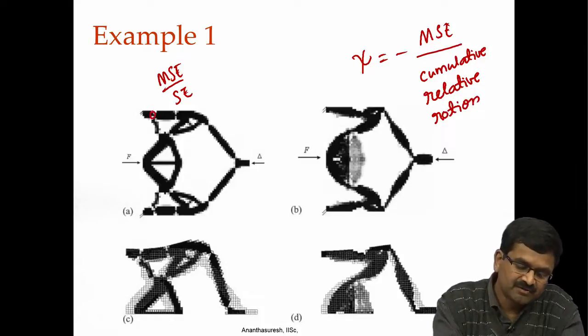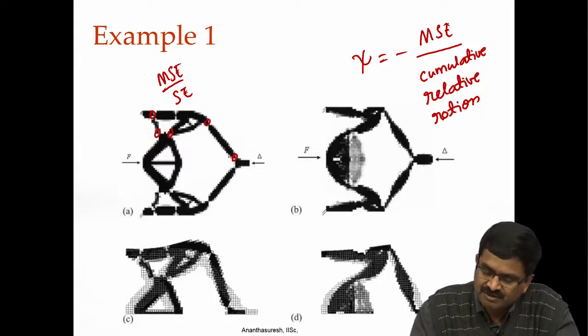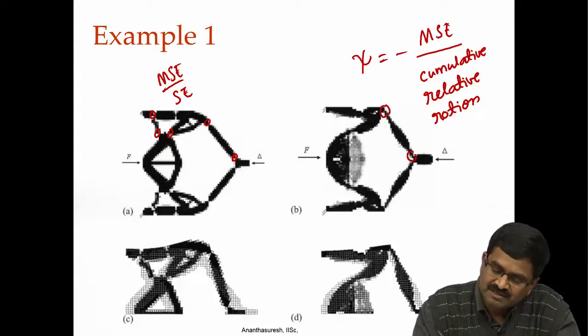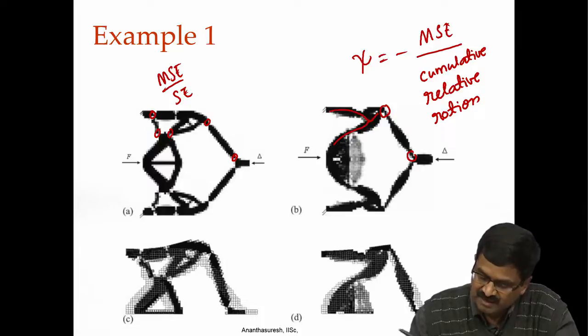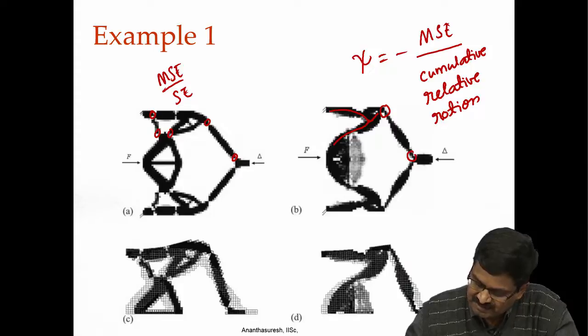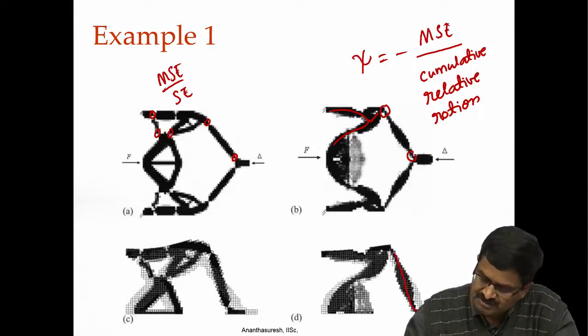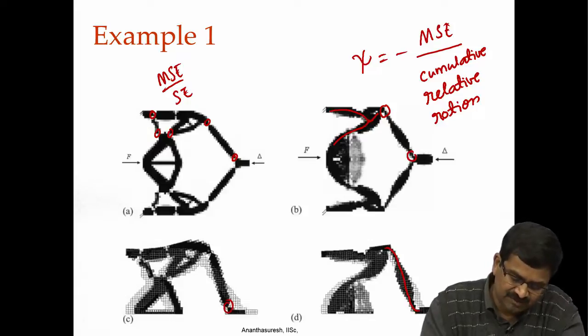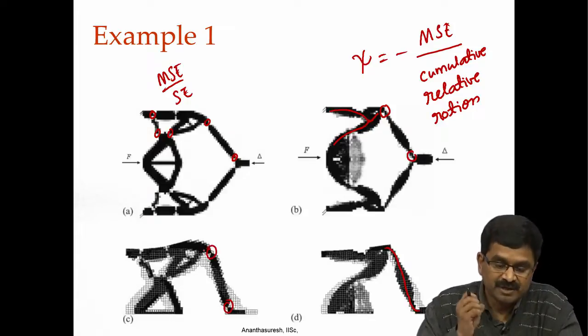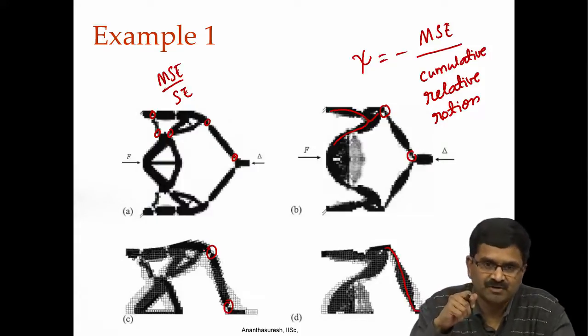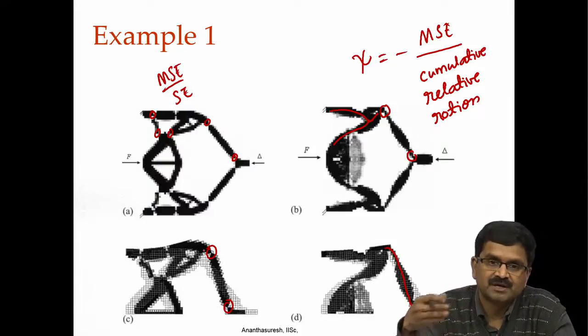You can see that we have joints, lots and lots of joints, right. Whereas here, are the joints not there? They are there actually. I am showing an example to show that somewhere else they have become more uniformly distributed, if you look at the top half, but other places it does have. But if we zoom in a little bit, adjust parameters, now you can see that at least it has become edge flexure rather than point flexure that happens here. Okay. So, by constraining or restraining relative rotation, we are able to go towards distributed compliance.